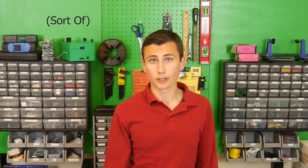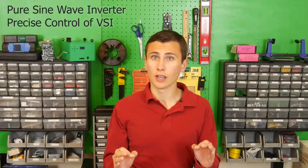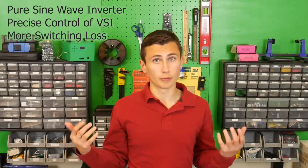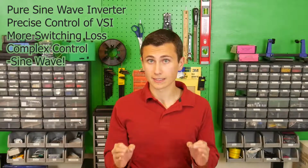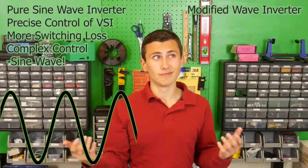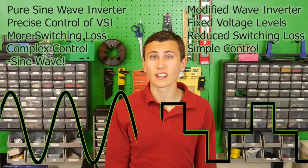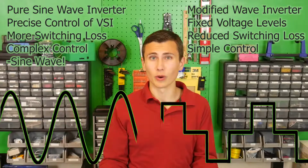Long sidebar avoided, the pure sine wave inverter uses very precise control of the output stage, at the cost of more switching losses and more complex control, to recreate that sine wave very accurately. The modified sine wave doesn't. Some modified sine waves even go so far to output a glorified square wave and call it a sine wave.